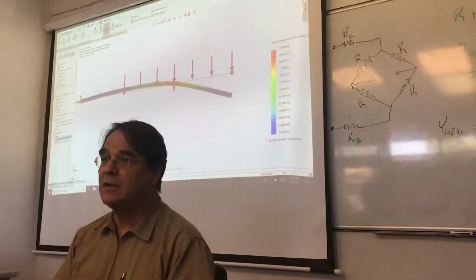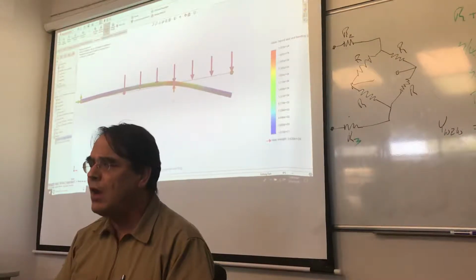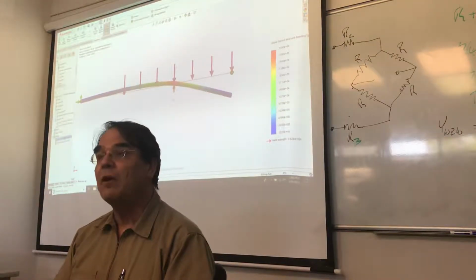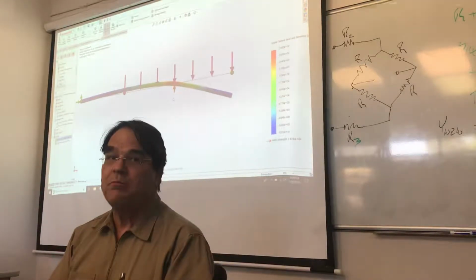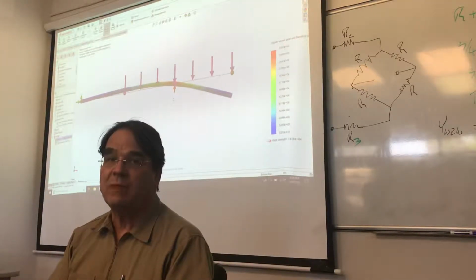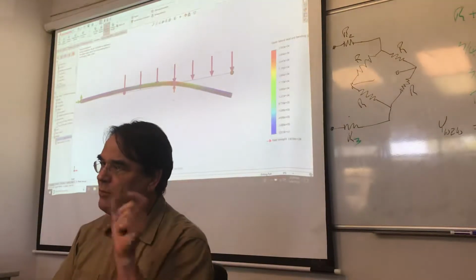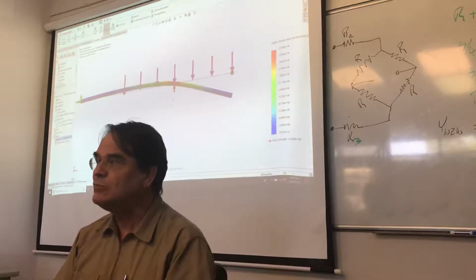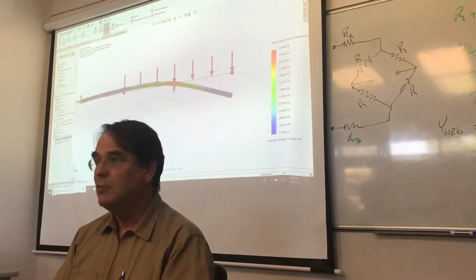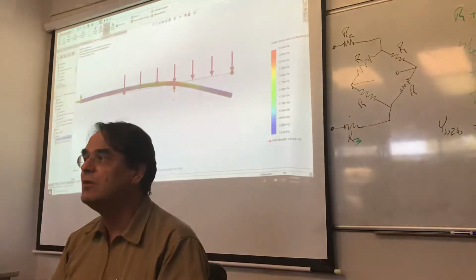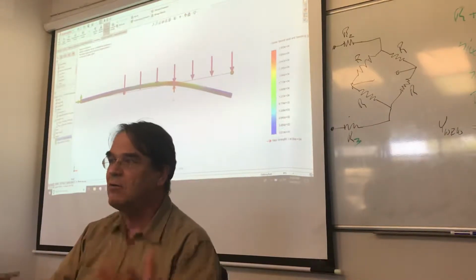We're also typically really only worried about the loads in the beams. We're not going to get information about the places where the beams come together. So if you're worried about the joints where we're joining the beams, you're not going to get it out of a beam model. Because it doesn't have anywhere near the detail about how the load gets in or out of the beam.